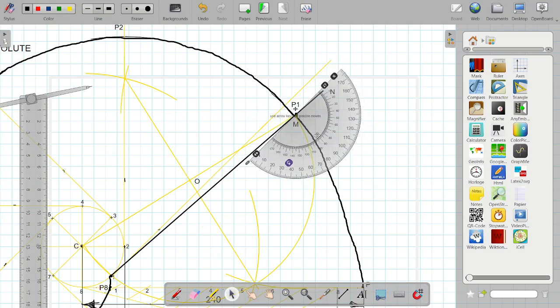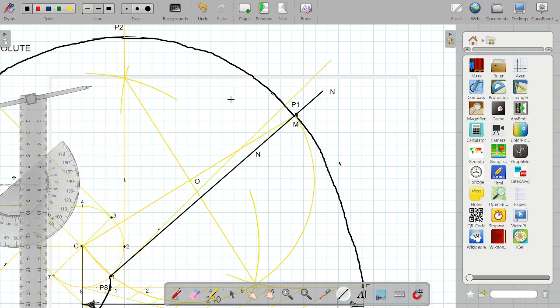So I will keep the set square at point M and mark 90 degrees with the normal somewhere here. And we'll join this line with point M, which is nothing but the tangent. So I will write this as tangent T and T.